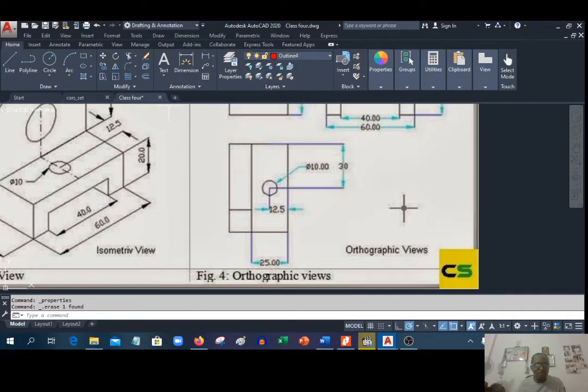So that it becomes obvious. So I'll come to Polyline. I want us to project from here. My beginning weight, enter, I'll put 10, enter, and my ending weight 10, enter. So once we come here, over here again, enter, my beginning, let me put 50, enter, and my ending 0, enter.